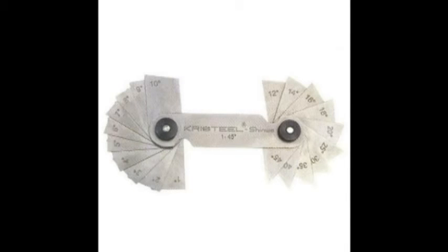Okay, so our next instrument is angle gauges. Angle gauges were developed by Dr. Tomlinson in 1941, which enable any angle to be set to the nearest 3 seconds. These are pieces of hardened and stabilized steel. The measuring faces are lapped and polished to a high degree of accuracy and flatness. They are 75 mm long and 16 mm wide and are available in two sets.